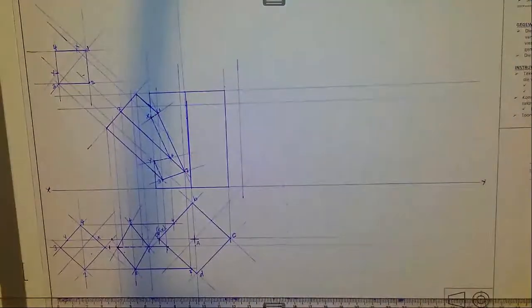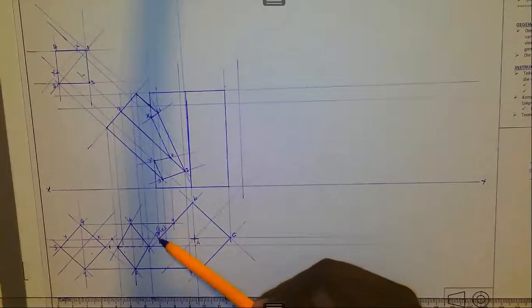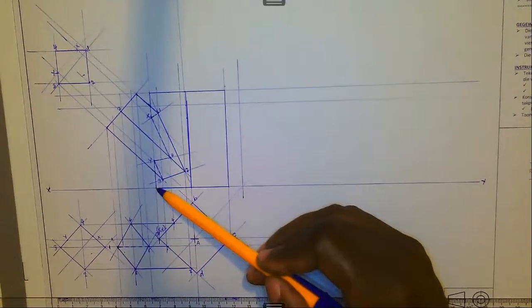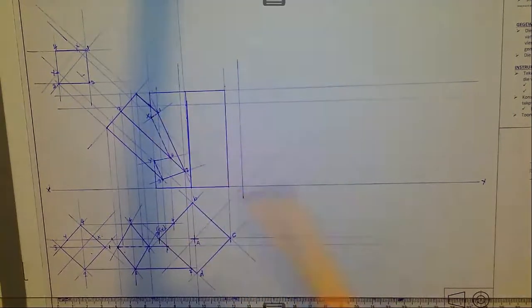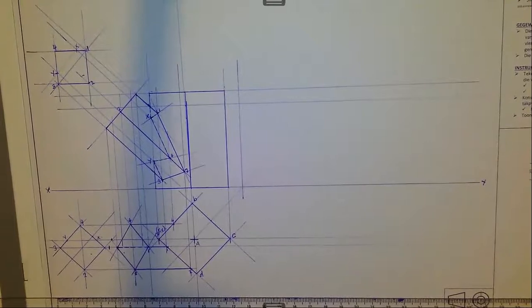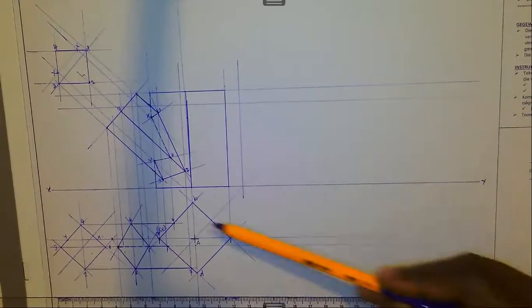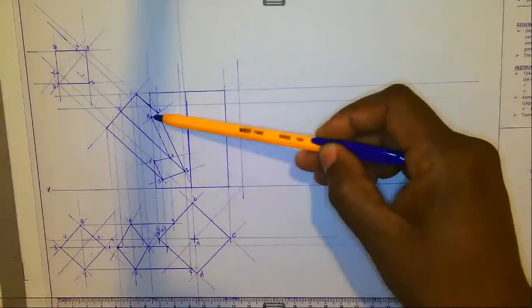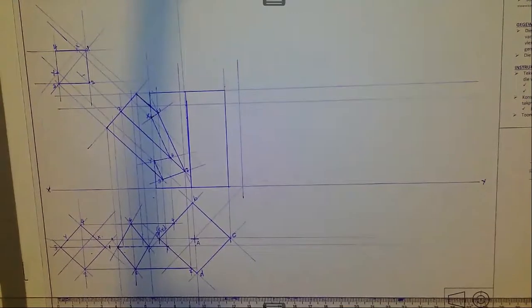In most cases, try to open through, if you are not given the seam, a part which would be shorter in terms of welding or sealing, okay? Remember, in industry they talk about time being money. You don't want to waste a lot of time welding from here to there when you can just join here and join there. So where possible, open through the shortest part so that you save on time and on resources as well.